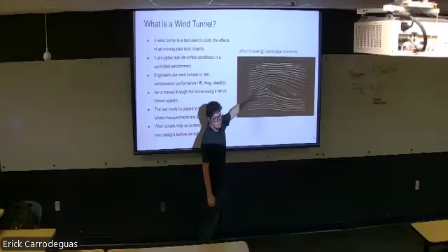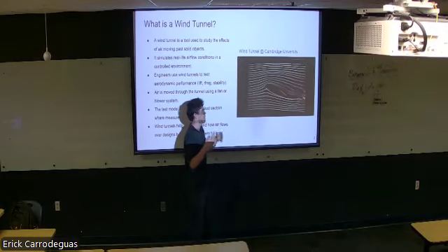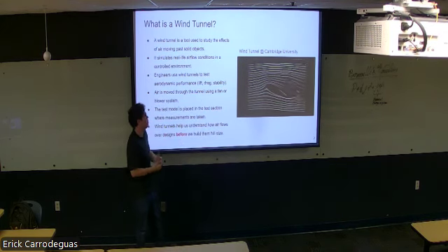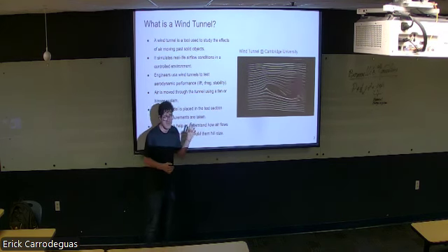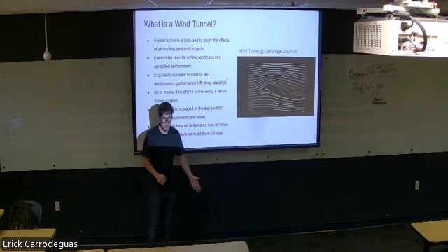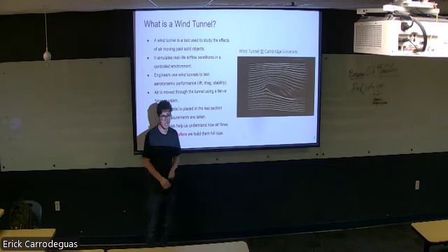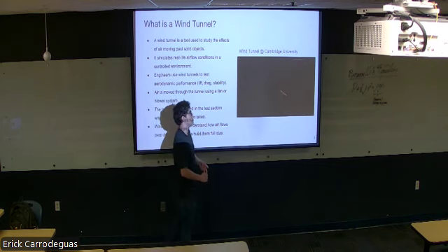It helps us test the airfoils. It's the particular shape of the wing. We can also test our plane models in the wind tunnel. We can test everything. But what's really good about the wind tunnel is that we can test it at any pitch. We can test any type of airfoil that we want in different conditions, like turbulent flow, laminar flow. We can test at different pressures and different Reynolds numbers.